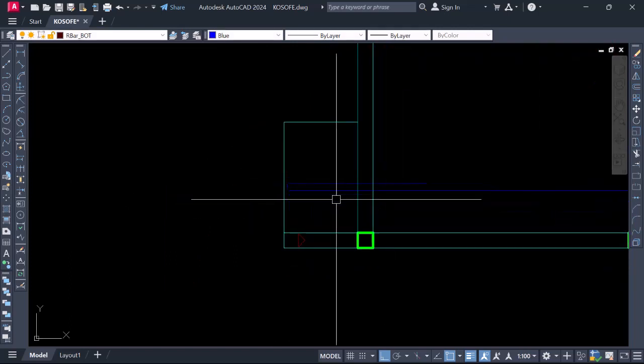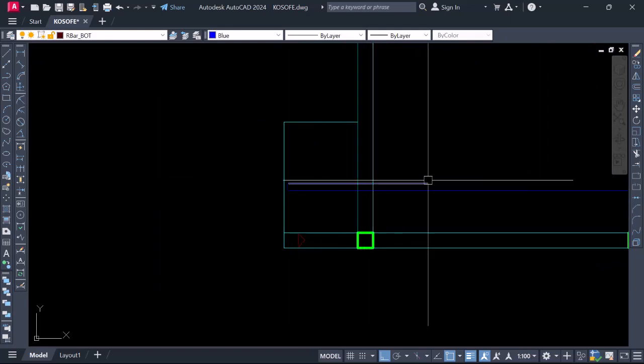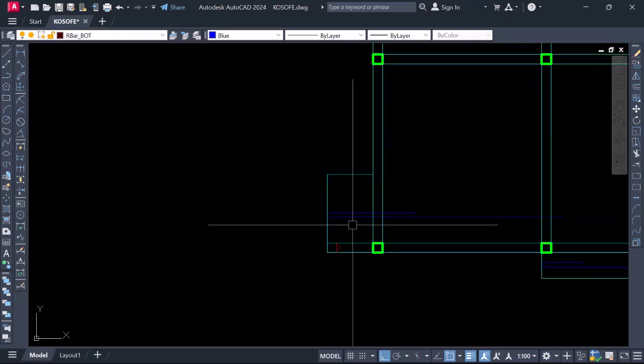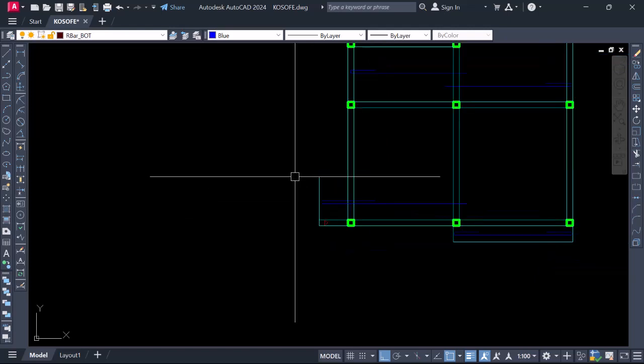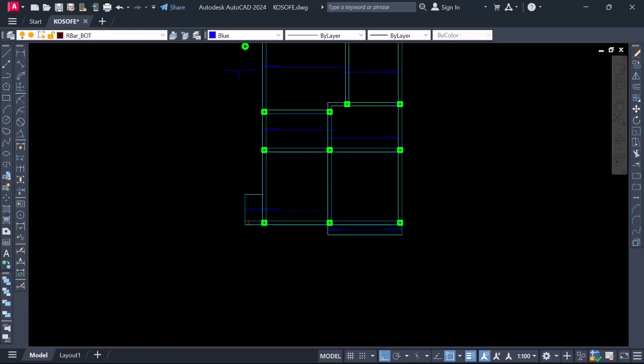All right, so it's going to extend from the cantilever. It's going to extend out down to the beam, and you continue your 80 because we have a cantilever here. So we always detail this area. I want this area to be doubly reinforced because it's a cantilever area. We're going to do the same thing over here when we are extending it in a vertical direction.